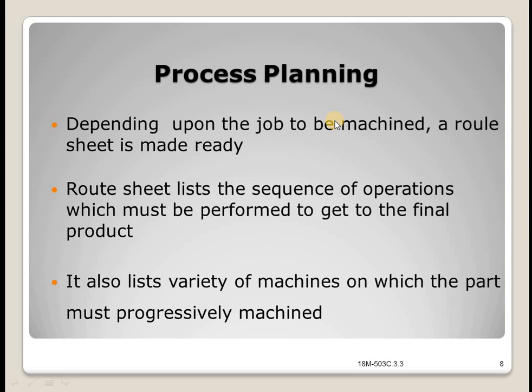Those are the operations required and their desired sequence, machine or equipment to be used for each operation, estimated setup time and operation time per piece, tools, jigs and fixtures required for the operation, detailed drawing of parts, sub-assemblies and final assemblies, specifications, dimensions, tolerances, surface finishes and quality standards to be achieved, specification of raw material to be used, speed, feed, etc. to be used on the machine tools for the operations to be carried out, inspection procedure and metrology tools required for inspection, packaging and handling instructions during the movement of parts and sub-assemblies through the operation stages.